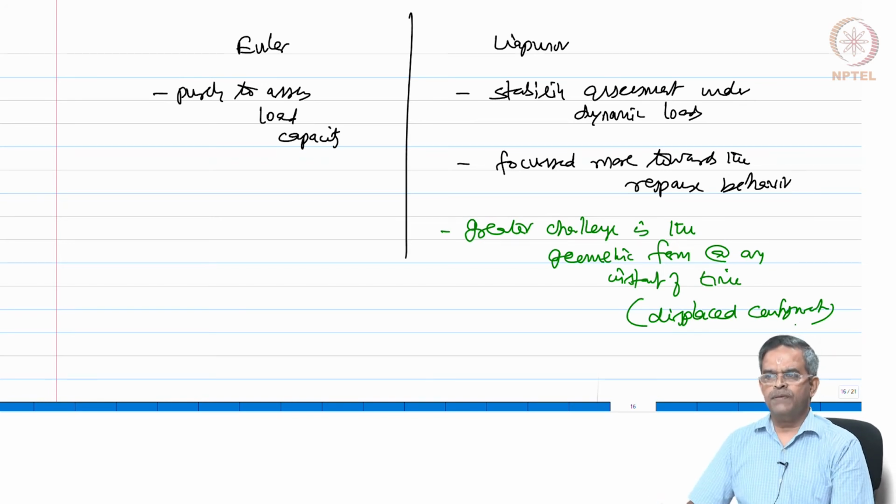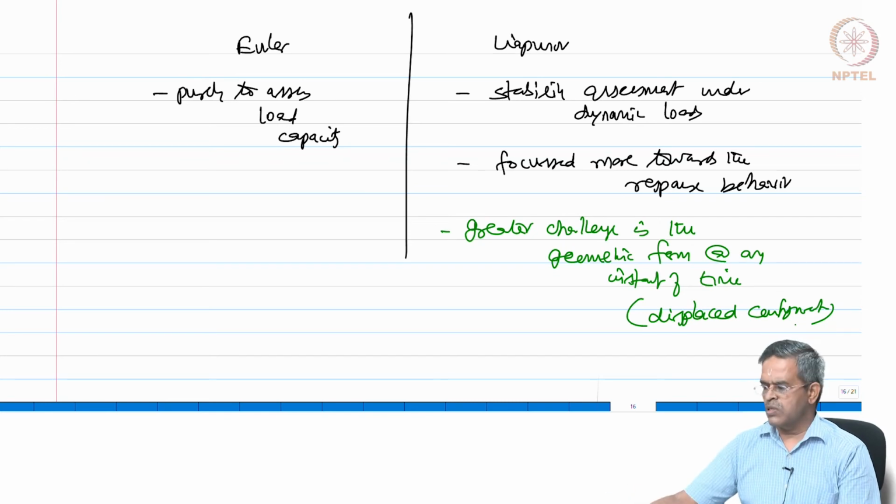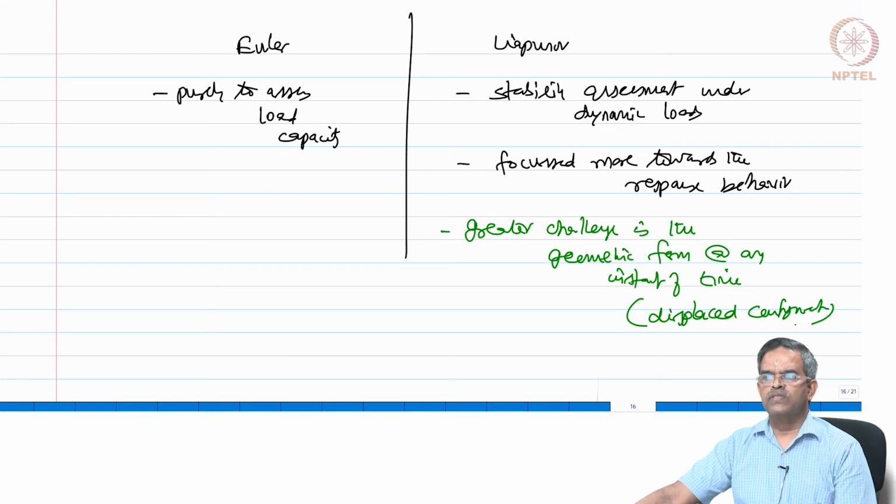Structural systems like ships, offshore compliant platforms, floating production platforms fall under this category of stability check. The stability calculations of ships, for example, focus on estimating the center of gravity, buoyancy and metacenter of vessels and their interaction.